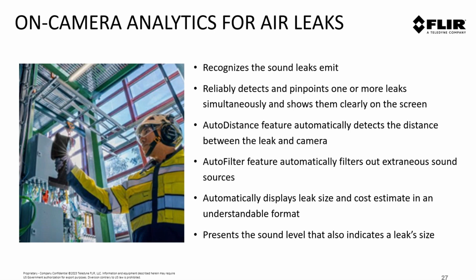Yes, I do see a question now. How far away can you be and still see an air leak? Yeah, it's always a great question. It depends. That's always the safe answer, right? It depends how far away it is and how large it is. It really comes down to the size of the leak and the distance. We can detect leaks up to, I think, 25, 30 meters away effectively, down to a smaller leak size. But I've done it where it's been 120 feet away because the leak was so large, we were able to isolate it pretty efficiently. So it really has to do with the size of the leak that you're trying to target.